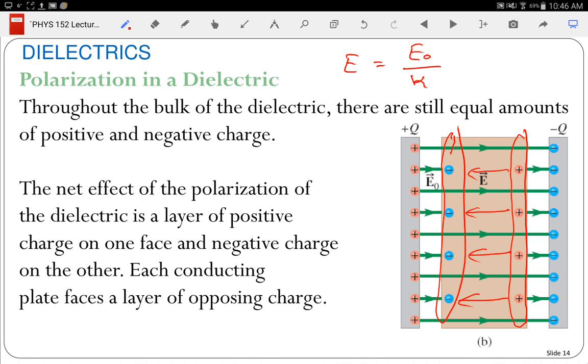Tori. So why is reducing the electric field strength advantageous here? Okay, why is it advantageous? Number one is that it increases your capacitance, and it's kind of hard to make big capacitors. Like in your car's audio system, capacitors store energy. Woofers use enormous amounts of energy, so you put a big capacitor, like a 1 farad capacitor, in your car's audio system so that you have enough power to drive the woofer without your headlights dimming. Right? Because they would do that.